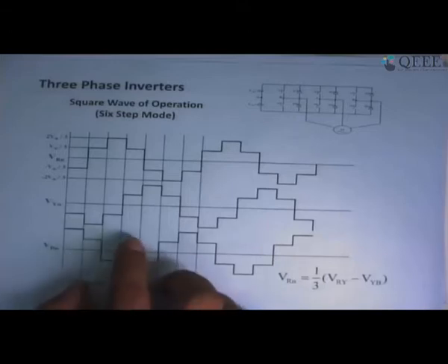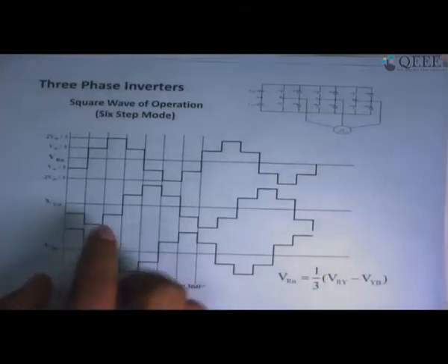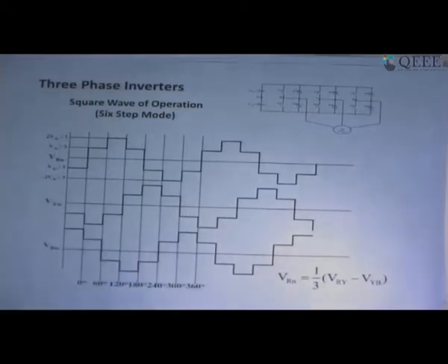We have also seen in the simulation that if you apply this kind of waveform to, let's say, a three-phase induction motor, the waveform of the current will not be good. It will also have a dominant 6th harmonic, which ultimately results in a torque waveform which is not pure DC. The torque waveform will have a dominant 6th harmonic ripple over a constant average DC torque.